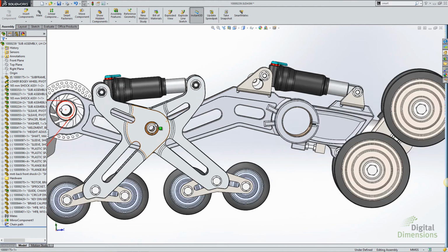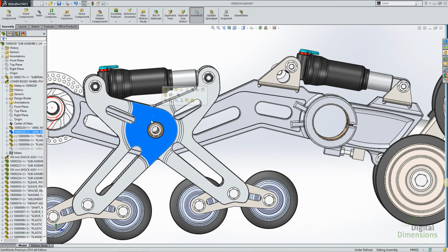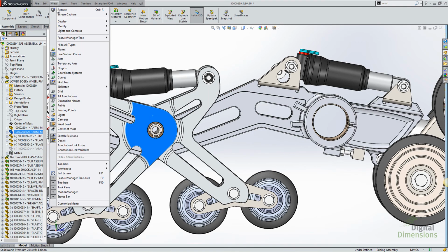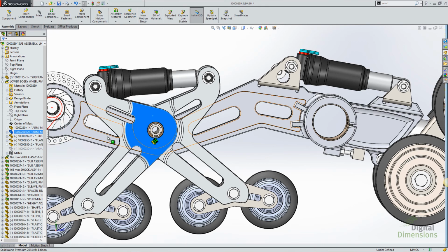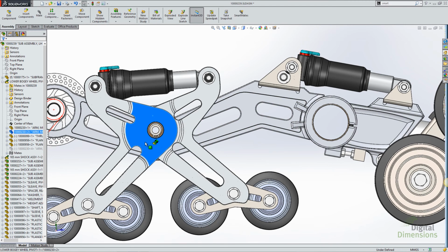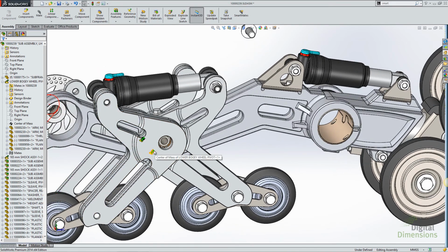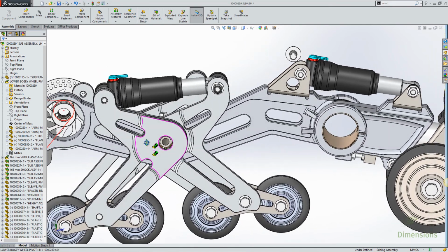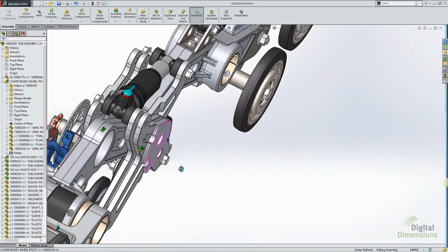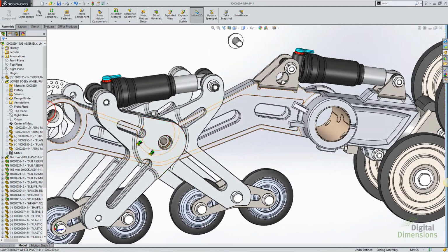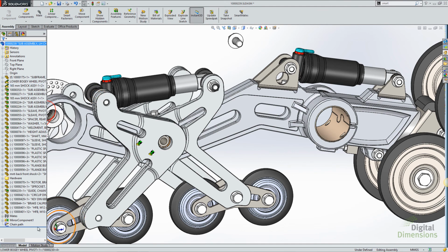Let's take a look at this assembly component. You can see that if I view my center of mass, the default behavior is that a mate is created so that the center of mass is aligned. However, if I go into this assembly, unsuppress a component, you can see that because it's mirrored, the center of mass shifted to the left with the addition of the other component, but it didn't give me the effect that I was looking for. The components are actually mismatched.